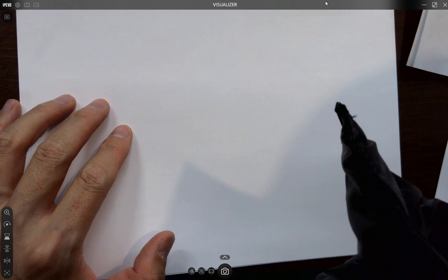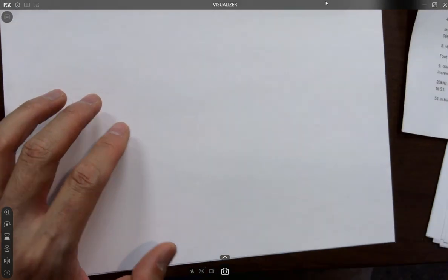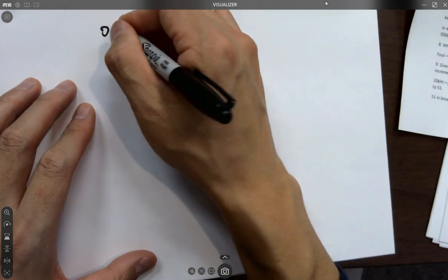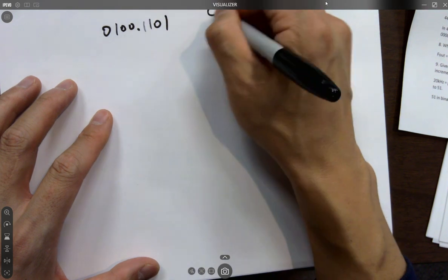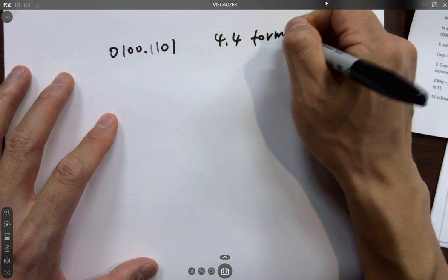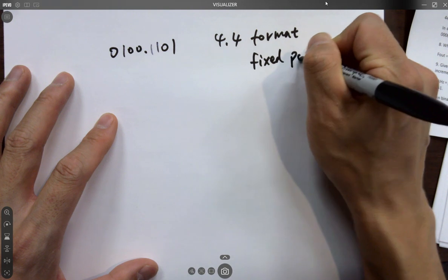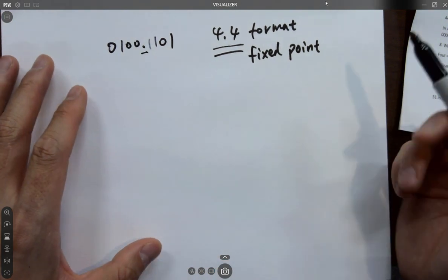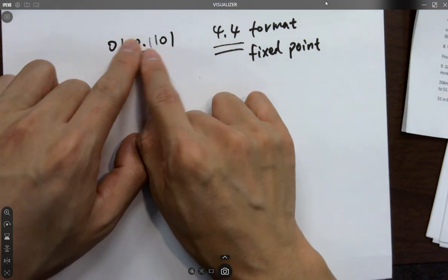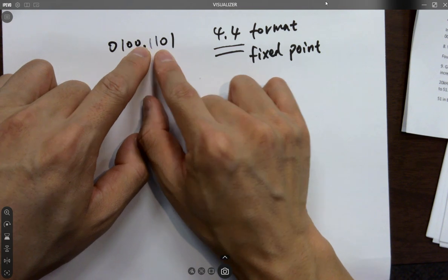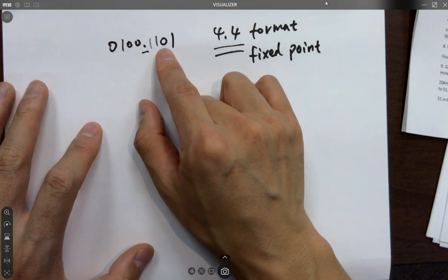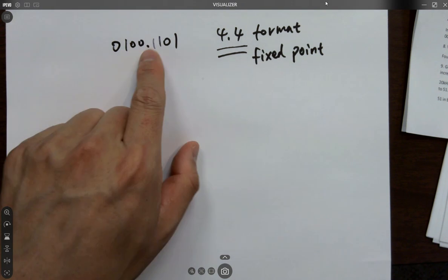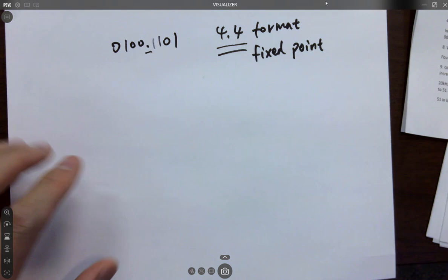Interpret that binary number as 4.4 format number. Like I said, right? So the register is storing 0s and 1s. It's just a digital number, right? You just have to tell the computer that you are using the 4.4 format as a fixed point format. There's no place to store a dot. You have to know that, right? It's just basically a register storing binary numbers. But you're telling the computer that anything is like four bytes here. The lower four bits will be the fractional number, and the higher 4 bits will be the integer. You just have to tell the computer this is how we format that number, okay? But the thing is, if you just look at the register, it's basically just these binary numbers. Just make sure you understand that first.